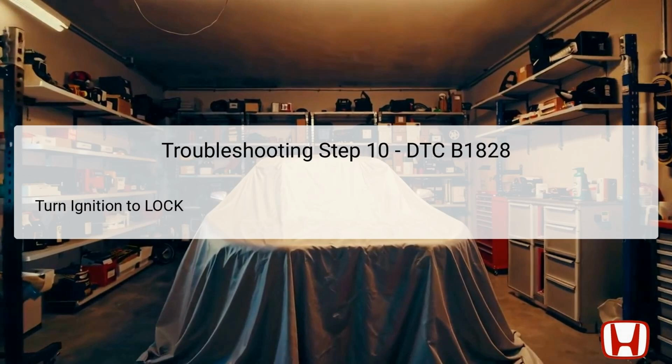In this step, turn the ignition switch to the lock position. This action is significant as it serves to disconnect power from the power seat control unit, which prepares it for further disconnection of the electrical components. Shutting off power ensures safety during subsequent inspections or repairs.